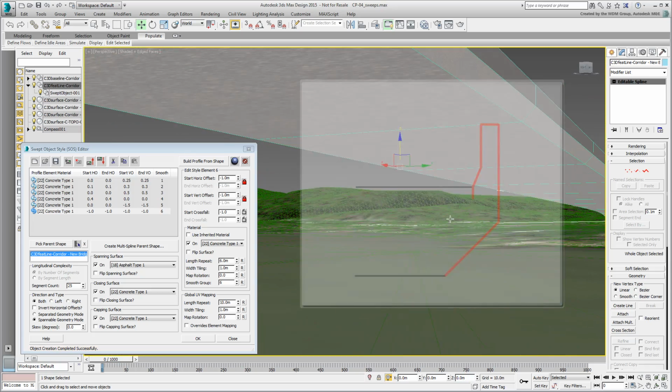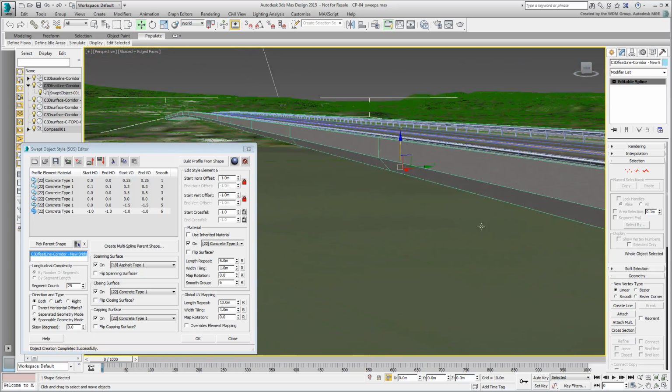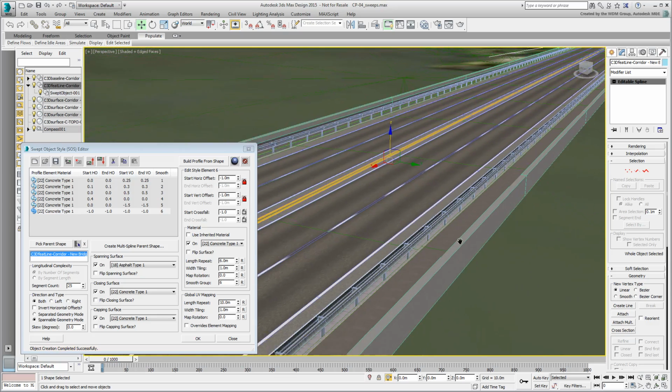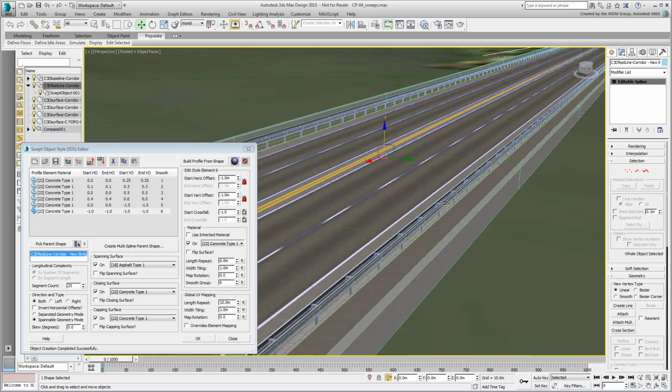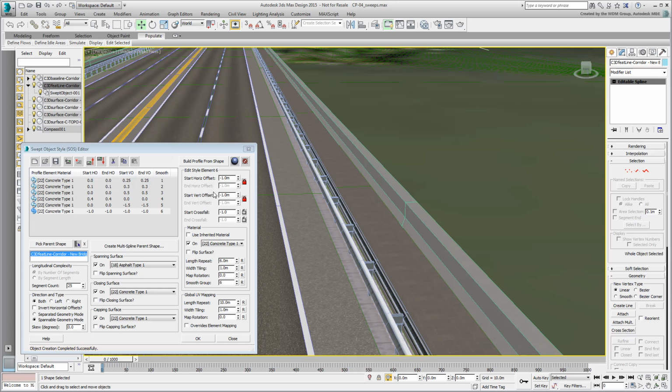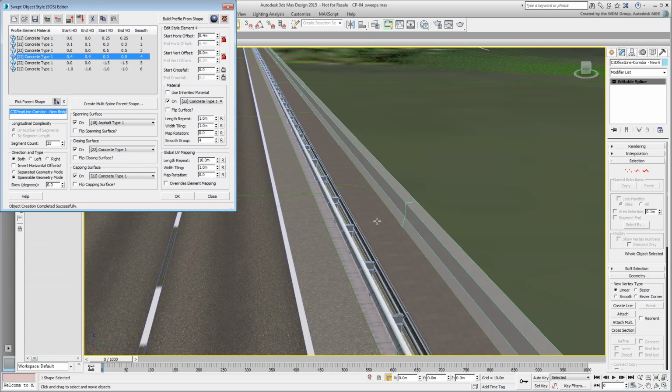You still need a fence, as the current height of the wall is not protective enough. Select the fourth entry in the list. It represents the top of the wall. Change the horizontal offset to 0.2 meters, and then copy and paste the element. You're back to the original width, except that it's now divided in the middle.